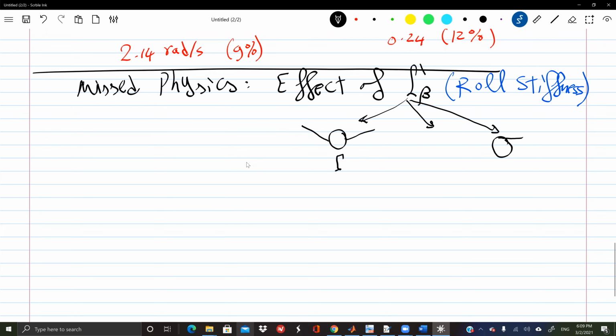Wing placement or sweep. Very good. Wing placement. If the wing is high on the fuselage, then it gives you more negative L beta. L beta is negative, of course. It must be negative for stability, and all these sources give you larger negative L beta. And like you guys mentioned, the sweep angle, right? All of these give you larger negative L beta.